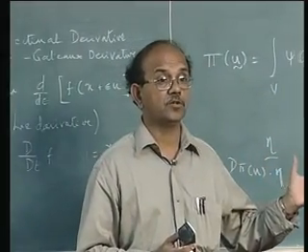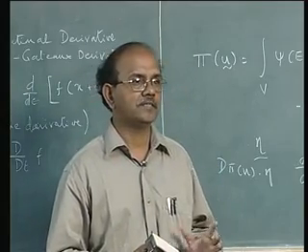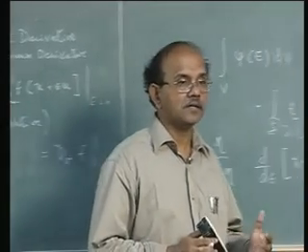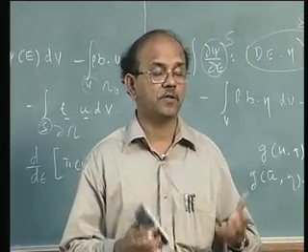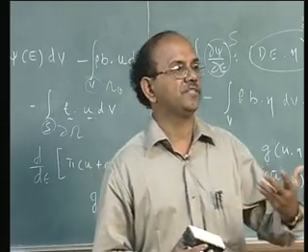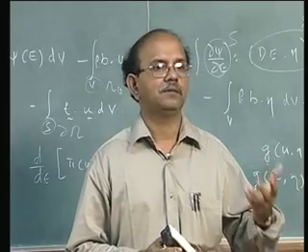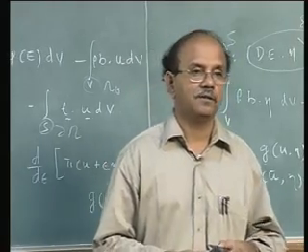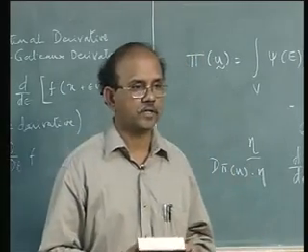Now, state variables are going to be defined at every point, and the only difference is that you can look at, as I said, deformation and temperature together, and the state variables are more than what you had studied. In fact, in a thermomechanical process or thermoelasticity, there can be 7 state variables, with 6 of them related to strain and 1 being temperature. In fact, you're going to see how we define temperature itself in thermodynamics. They're going to be different from what you probably studied before.